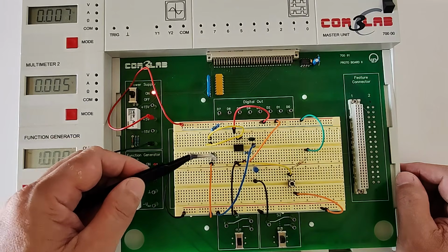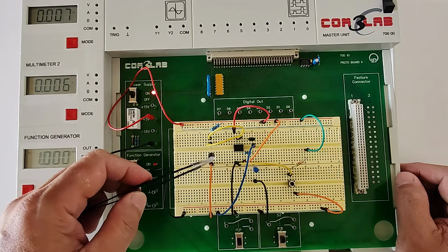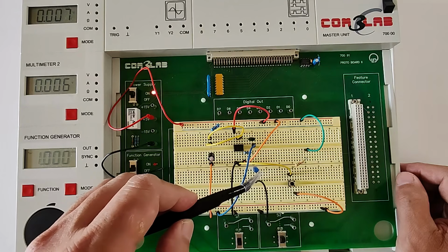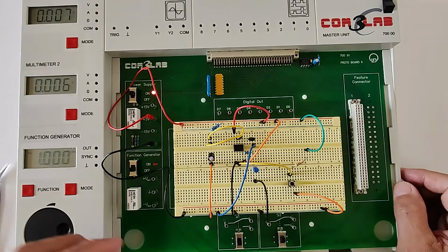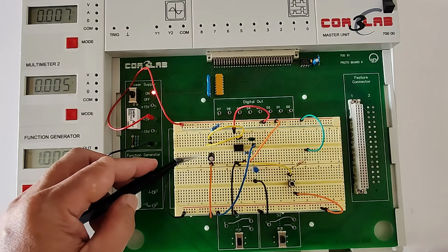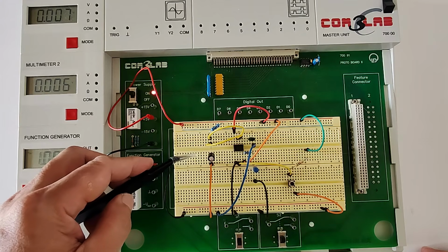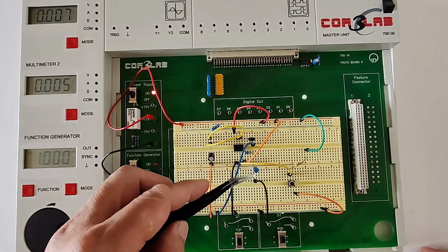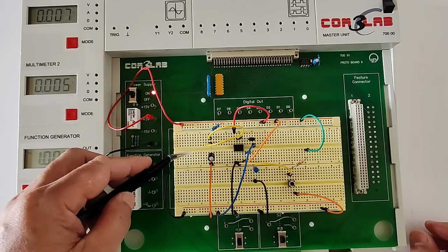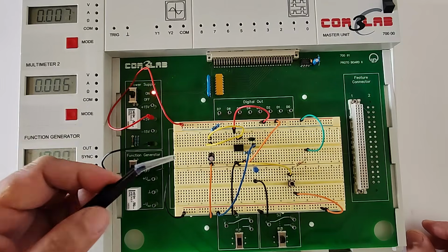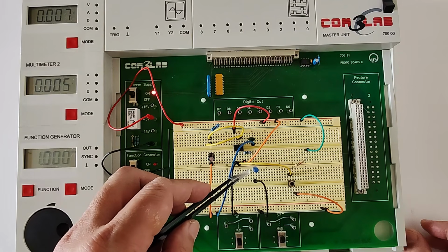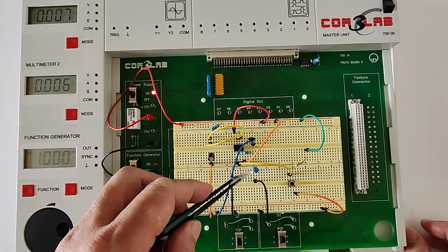Now, the charging and discharging time of that capacitor will determine exactly how long that on state is. Which means, if I change the capacitor to a different value, let's say from 47 microfarad to a lower value, let's say 10 microfarad, we expect the on state to be shorter. Now, if I change the capacitor to a higher value, let's say 100 microfarad or 220 microfarad, for instance, we expect the on state or the unstable state of our multivibrator circuit to be longer.